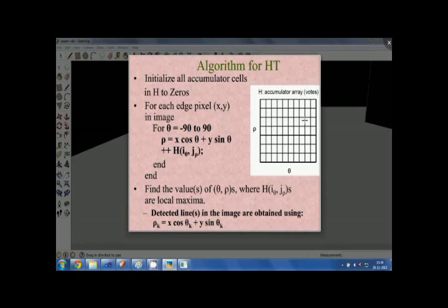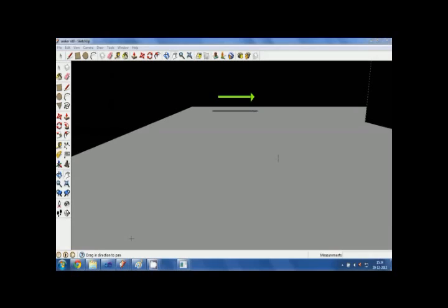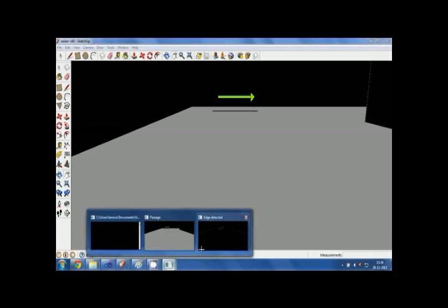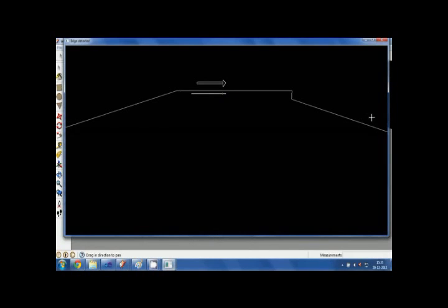This method only returns to us the slopes and the perpendicular distance. It does not tell us exactly which line segment is there in the actual image, but you'll find that that's actually enough for our purpose, because if the image that we are using has only these two lines, we only need to sum their slopes, and we found out how we can get the slopes from this method to get the center point of the line, and always try to make our robot move towards that center point. So that very simply is a way by which you can implement lane following.